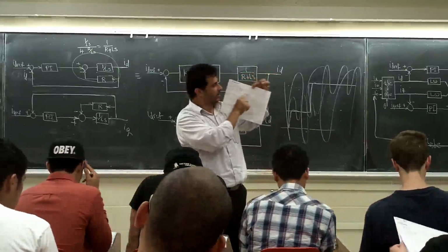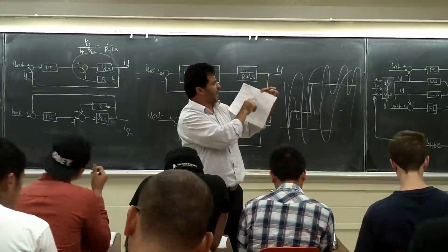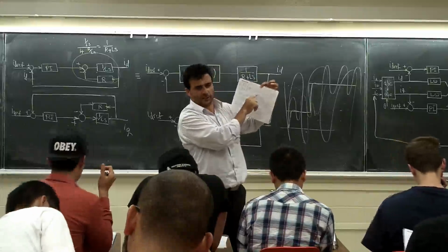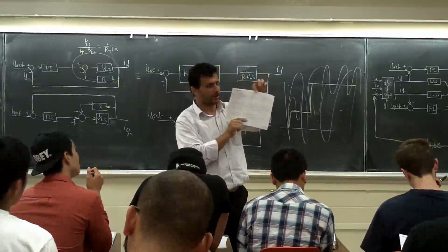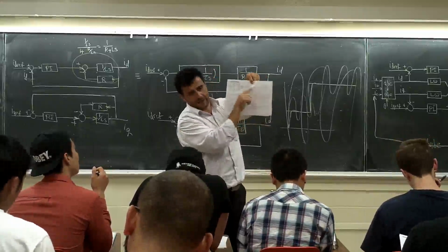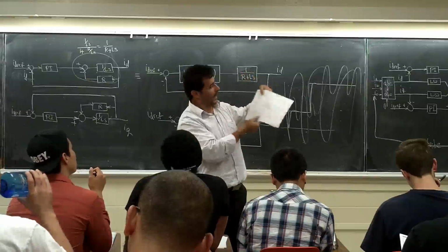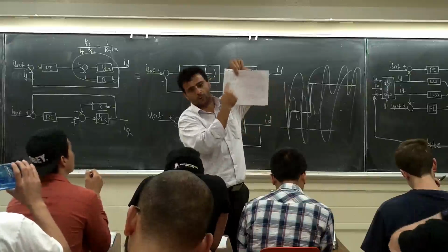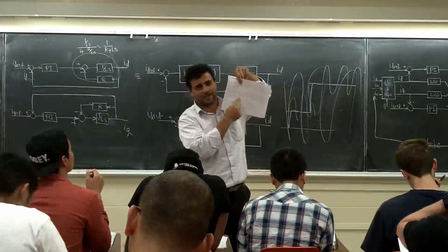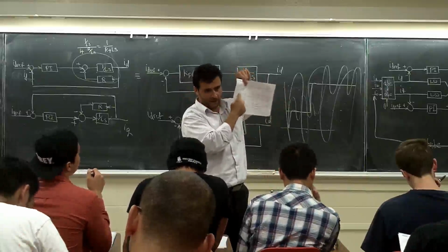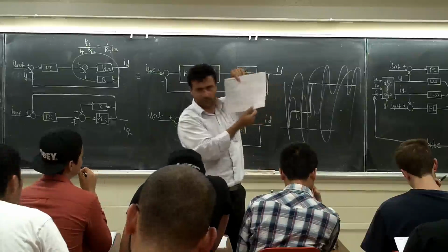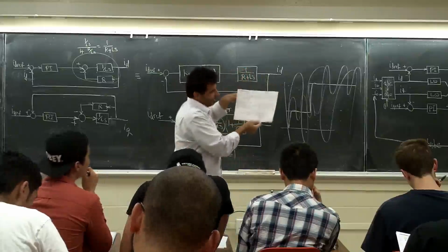Different notation. I just said how to calculate VAG, VAN, VNG. This is better because it's N and G, not NN, so it's not confusing. And we went through this equation. We calculated all these equations here. And here, this is what we proved: if we design the PWM, it is going to be those equations. Remember, they're similar triangles. I'm going to upload this one also on the website. You will have it.